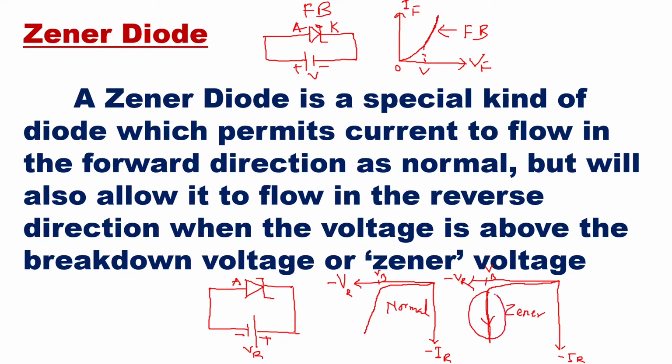This part is very important. You have the breakdown voltage as a constant voltage, but the current can vary from one point to another within certain limits. This variation in the Zener current is for a fixed voltage, whatever is specified by the manufacturer, whether it is 6 volt or 12 volt or any other value.